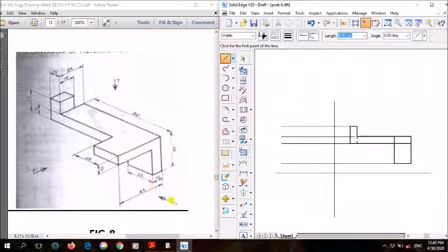So this right view will be drawn on the left side of your front view. So next here in the right view, this whole L surface, that is inverted L, this whole surface is visible, and above that only this part is visible, right? So this L surface and this surface is visible, so that will be drawn in the right view. So after that, we'll see what are the invisible surfaces that need to be drawn using dotted line. So first we'll draw these surfaces.